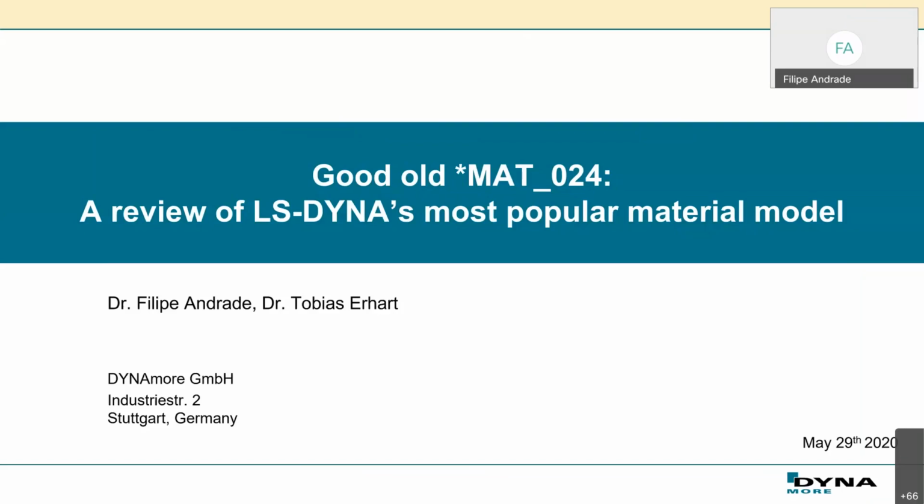And sometimes when you don't know which material model you have to use, people very often just go back to Mat24 and try to do something with that. And that's why I thought it might be an interesting thing to review it a little bit here today. I still believe it's probably the most popular material model in LS-DYNA.